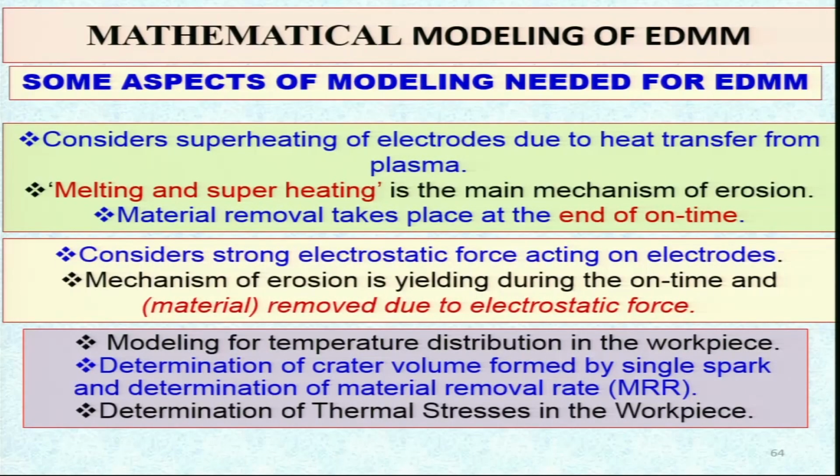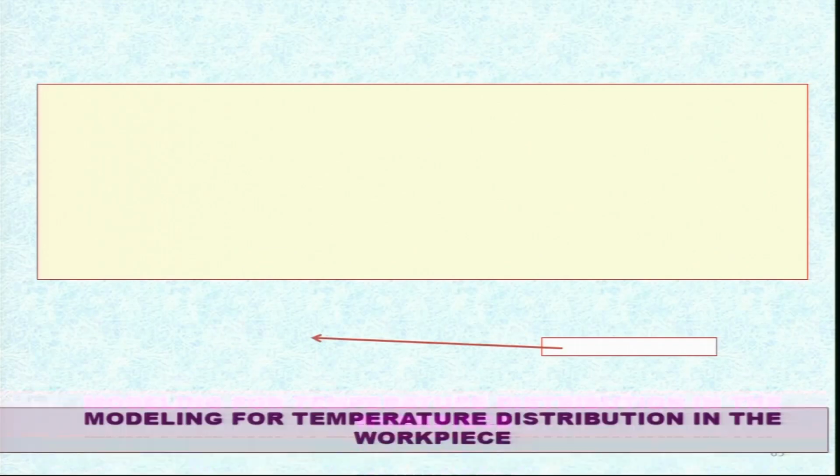Determination of thermal stresses in the workpiece is another important aspect, because there should be minimal thermal residual stresses in the machine component. Otherwise, it may fail during its use, prior to its estimated life.